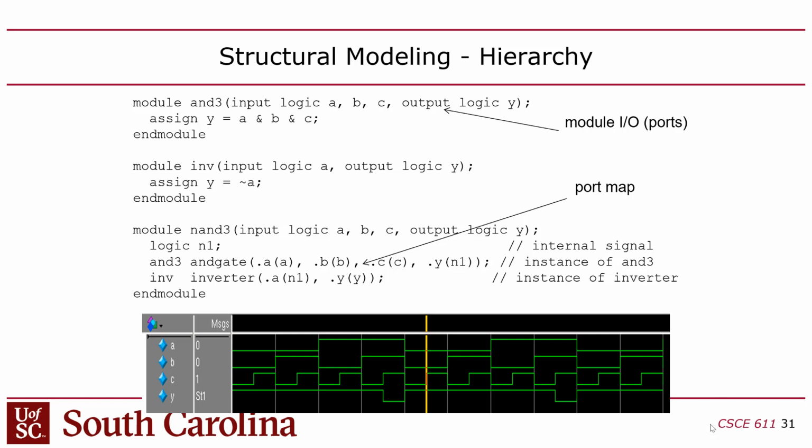You can either start at the beginning and say, all right, let's look at the clock. Do we have a clock? Because that's my heartbeat. All right, I got a clock. Okay, now the next step is, do I have a sequence of instructions coming out? Okay, I've got that. I look at the ports of the register file, or the right sequences of registers being written and read. And so you can start like that, or you can start from the end, and you can look at the wiring to the hex displays, and you can trace it back to whoever's setting that and figure out why it's not setting that, right? And go backwards. Does it make sense? Okay. So the whole idea is that you're looking at the waves, comparing what you're seeing to what you expect to see there.